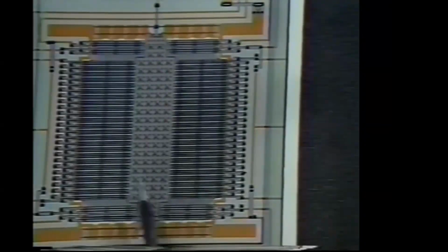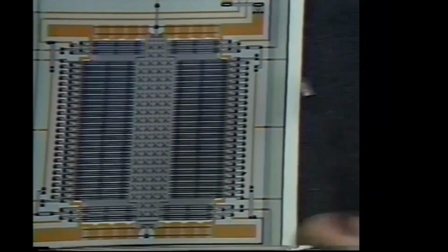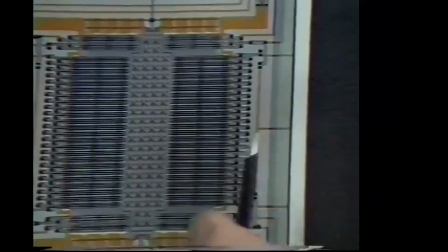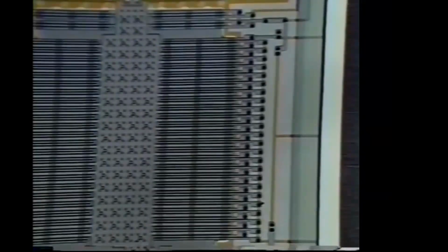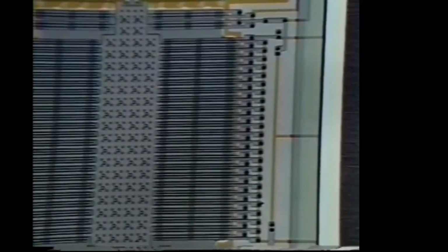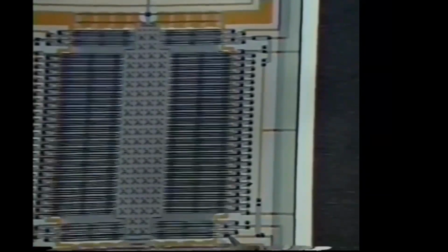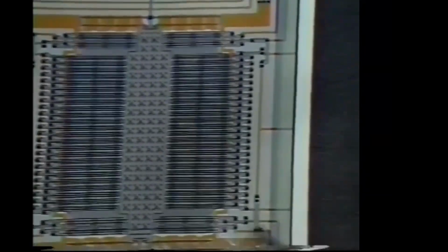Here you see a wider proof mass. This is a folded suspension which automatically stress relieves the polysilicon. And in some cases, we actually use the polysilicon as crossovers of some of the signals. So that, and the fact that the sensor was placed in the center of the die, were some of the improvements. But in a force rebalanced architecture, you don't need all of the fingers to sense and all of the fingers to force. At 5G full scale, we separated force and sense, again allowing a reduction in the noise and improvement of the overall system performance.